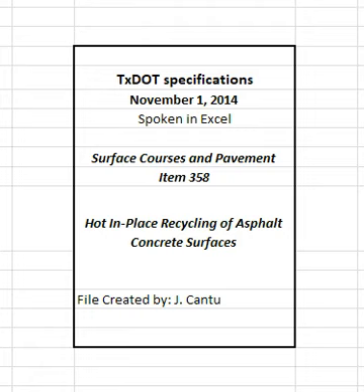2.2 Hot mix asphalt. If the process requires additional HMA, furnish new HMA that meets the requirements of Section 358.4.2, Mixture Design. Use materials meeting the requirements of Article 340.2, Materials, to produce the new HMA. Other HMA mixture types are allowed when shown on the plans.